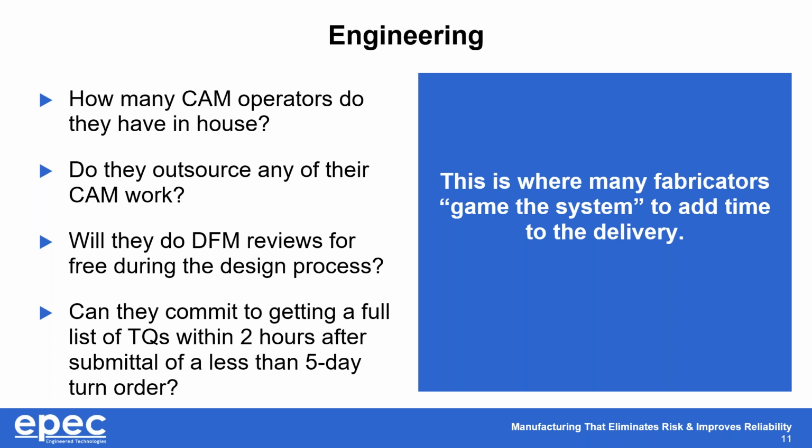Because if we can't get out of engineering on a 3-day turn within 2 hours and get into imaging, we're going to be late. There's just no physical way to do it. We have to be able to move that quickly. And that's why working with a fabricator who really wants to be involved in your design and is willing to invest in the CAM resources to do free DFM work for you is really important.